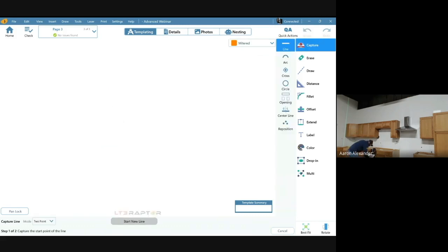Now I'm going to jump into cabinets, line. I'm even going to use auto fillet here because I love auto fillet. I'm going to start again on my crossliner target, that slider target I got set up down there, representing that edge. I'm going to shoot on that first. And then I'm going to come down here and shoot right onto the bottom of this upper here. There's our first edge. Now I'm going to come right around to the left side, shoot 2 points on the left side here. There's 1, there's 2.